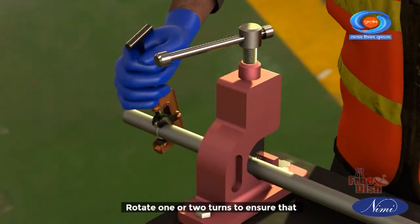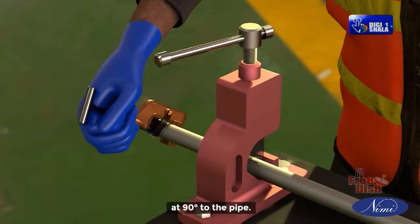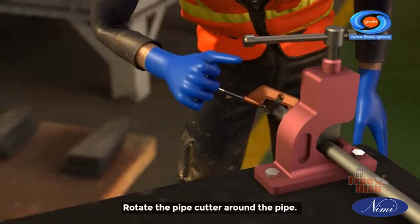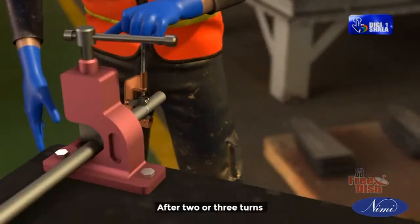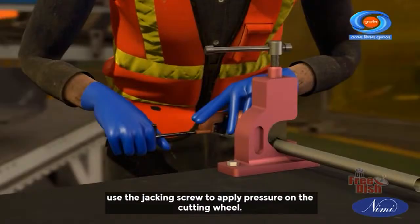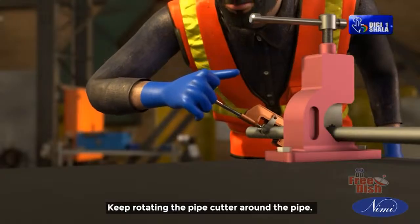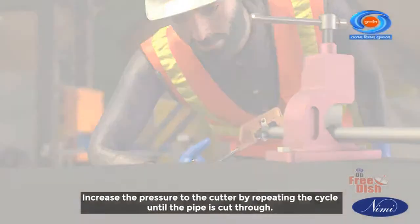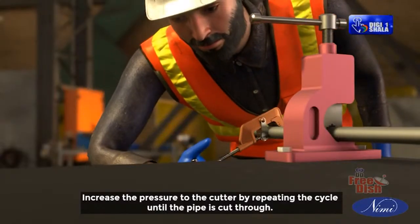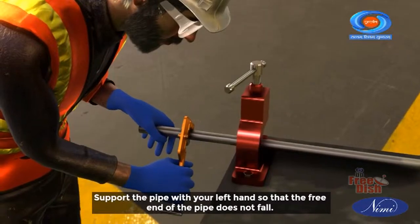Rotate 1 or 2 turns to ensure that the cutting wheel is sitting exactly on the scribed line at 90 degrees to the pipe. Rotate the pipe cutter around the pipe. After 2 or 3 turns, use the jacking screw to apply pressure on the cutting wheel. Keep rotating the pipe cutter around the pipe. Increase the pressure to the cutter by repeating the cycle until the pipe is cut through. Support the pipe with your left hand so that the free end of the pipe does not fall.